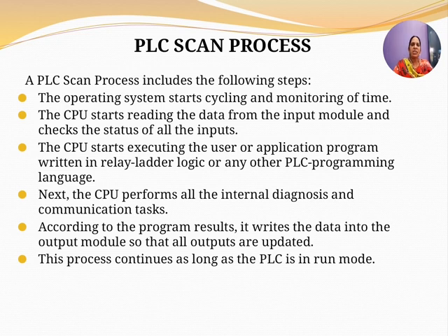So the operating system in the PLC scan process, what does it do? The operating system starts cycling and monitoring of time. The CPU starts reading the data from the input module and it checks the status of all the inputs. Then the CPU starts executing the user or application program written in relay, ladder logic or any other PLC programming language. Next, the CPU performs all the internal diagnosis and communication tasks. According to the program results, it writes the data into the output module so that the outputs are updated.